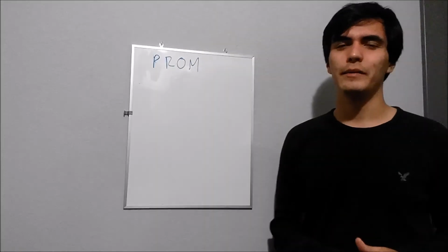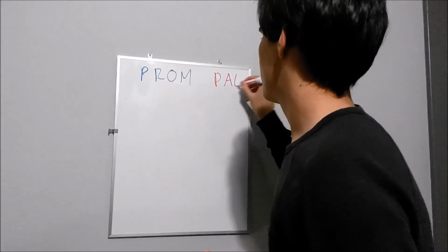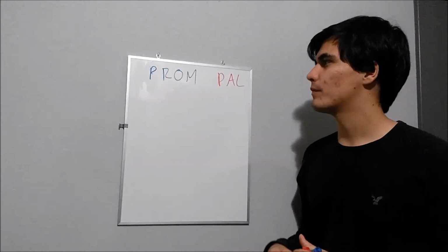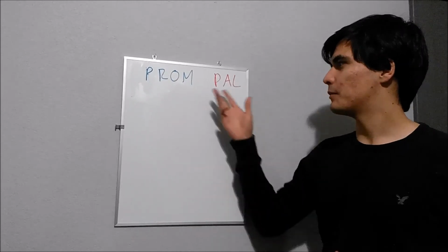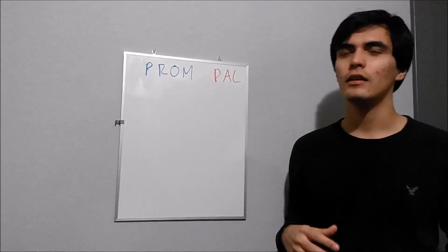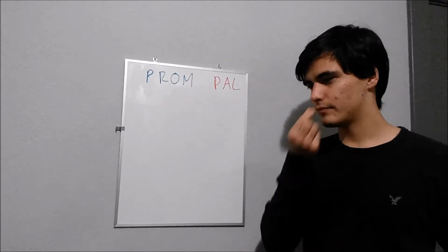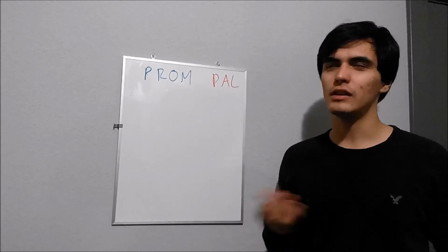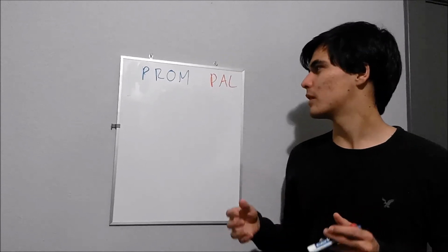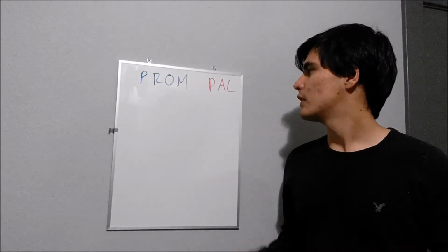In the PLDs we have a device that is called PAL. The PAL device is like a PROM memory, and it works like a PROM because it has fuses in the array of AND gates in the inputs, and to program it you need to blow the fuses that you don't need in the inputs, and it will pass all the data you have through the output.